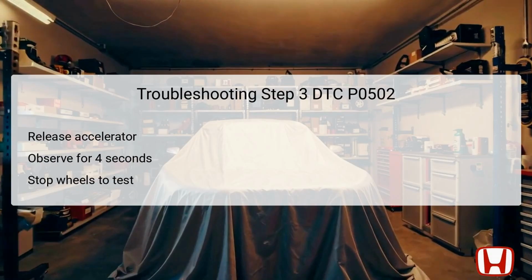process. The next step involves carefully releasing the accelerator pedal after maintaining 1,000 RPM for a sufficient time. The technician should observe the vehicle's behavior for at least 4 seconds during this release phase.